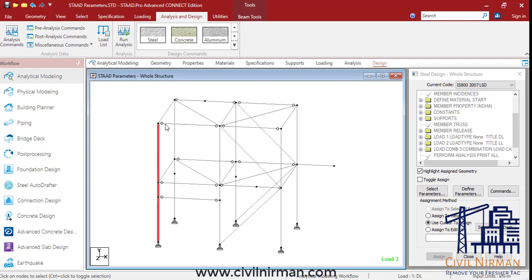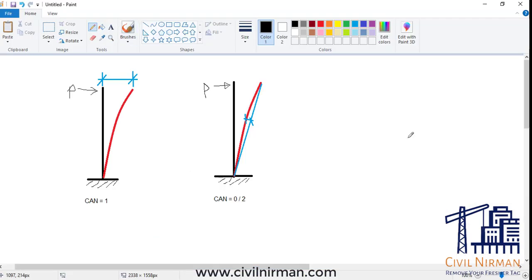What do we mean by lateral? That's a horizontal displacement. As I was saying, if we have a simply supported beam like this between our columns with a vertical load, the displacement curve will be somewhat like this for this member. So this we consider as a vertical displacement. And if we consider a column with a horizontal load, this column will try to displace something like this. So this is the displacement value and this is a lateral displacement. Lateral displacement is nothing but a horizontal displacement.